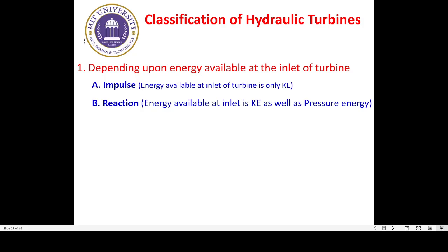As the water flows through the runner, the water is under pressure, and this pressure energy changes progressively into kinetic energy. Thus in the case of the reaction turbine, the runner is completely enclosed, placed inside an airtight casing, and additionally the runner as well as the casing are completely full of water.